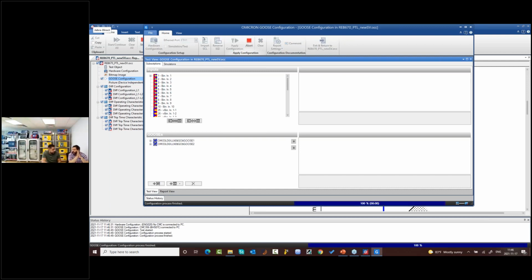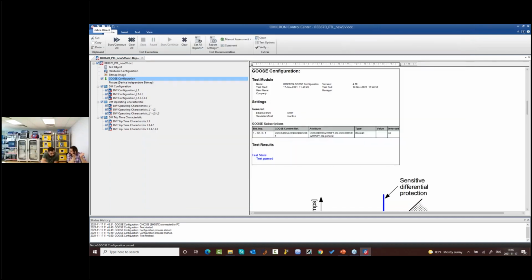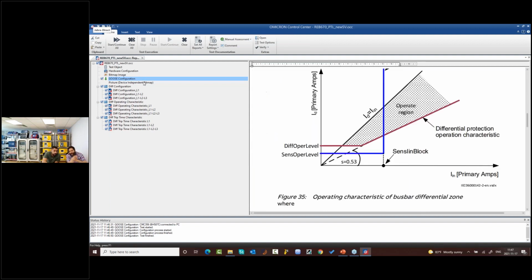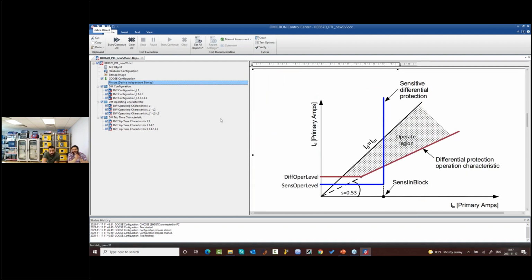Sorry, I have to interrupt you, but for the analog system, you don't need this at all. Only current needs to be configured, 6 outputs connected to one feeder, in the same file, by the way, and you will inject the analog current instead of sample value. Then I put here this image from the relay manual to show you that in the testing file itself, you can add some helpful information, like the boost module, how to connect it, or warnings.